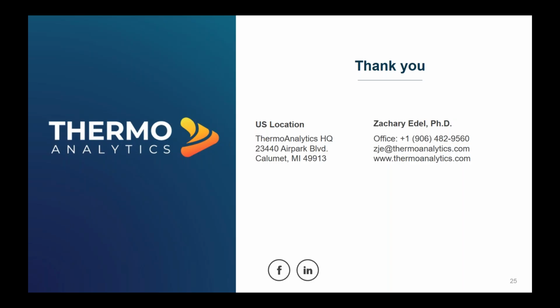What other battery modeling capabilities are available from Thermoanalytics? We have a thermal runaway model that we're using along with the CFD venting model to predict the propagation of thermal runaway in the pack and the effect on the surrounding vehicle geometry. We also have a battery lifetime model, and we do have some electrochemical cell modeling capabilities through PyBAMM's open source library.